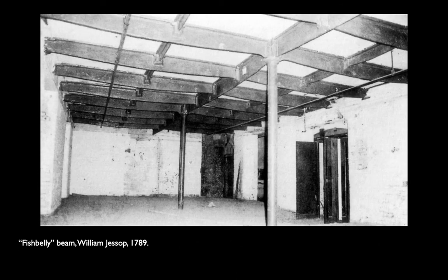Here are those fish belly beams in practice. Cast iron columns, cast iron girders, cast iron beams. You get a sense for the kind of clumsiness of the connections, right? That these are not ever going to be rigid connections because of the imprecision of cast iron, and all of that masonry around the outside is what's going to give the building its lateral resistance.